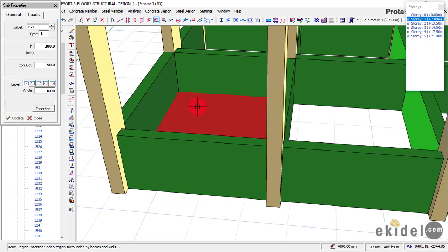So in this case, our depth of beam is 1.7, which is 1,700 millimeters, and our slab is 200. So 1,700 minus 200 gives us 1,500. And if we now subtract 50 from that 1,500, that gives us 1,450 millimeters. So our height of level now becomes 1,450.